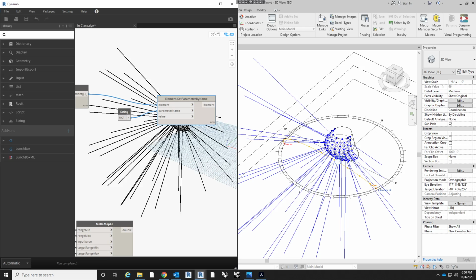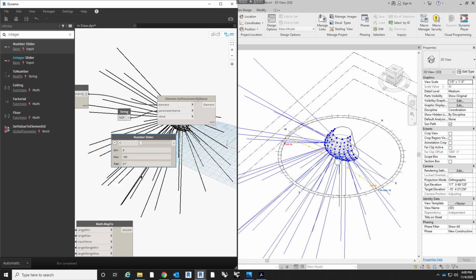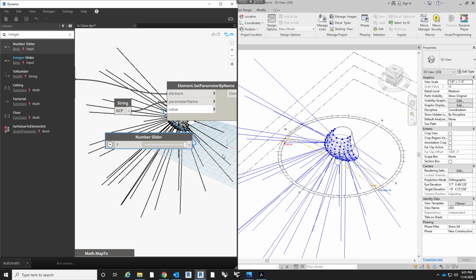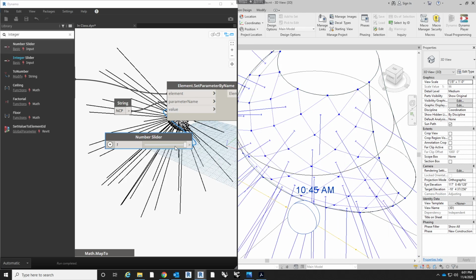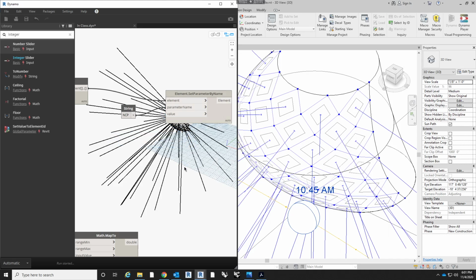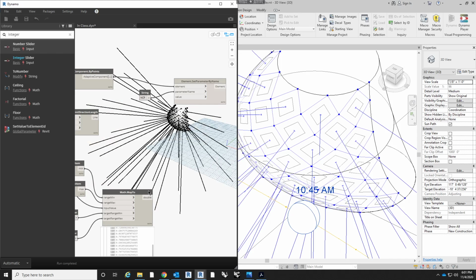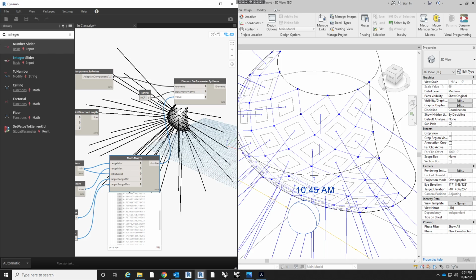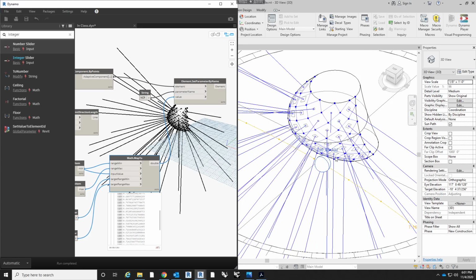And then before we plug this in, we can go in and plug in any value that we want between 0 and 1. So if we do a number slider between 0 and 1, and let's say our step is 0.001, if we plug that in, it's going to influence the whole series of panels, right? So we can control all these panels based on the number slider that we just created. All right, but we want this to be parametric to the sun. So instead of doing that, we can take our newly remapped numbers, plug that into the value, and this might take a minute.